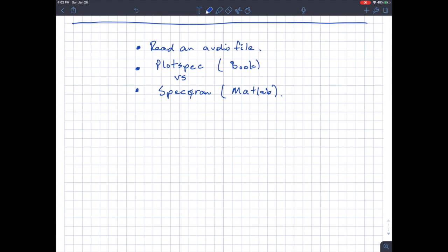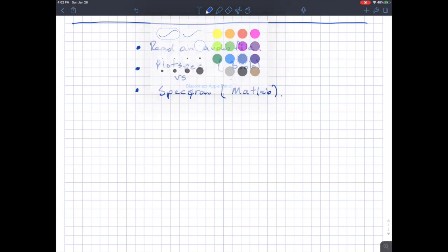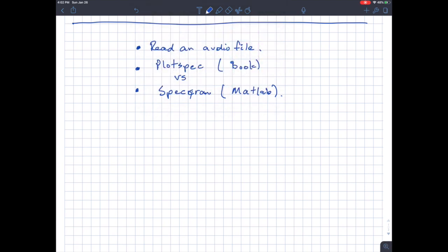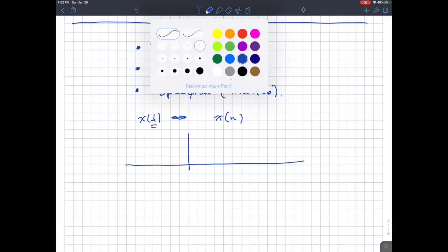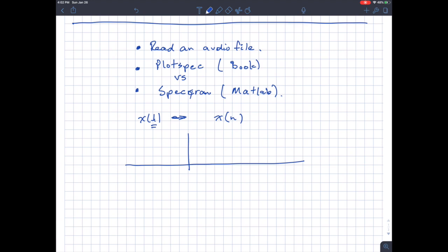Okay, so let's get started by thinking about sampling. All right, so let's say we have a signal x of t and it's sampled, and so essentially we get a digital version of that. I would call that x of n because now we just have samples instead of values for all t. All right, so what we know is that when we sampled, the spectrum of the signal got replicated. Okay, so if it originally looked like this,